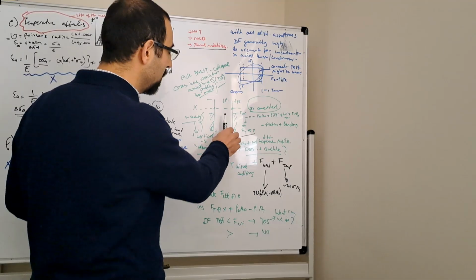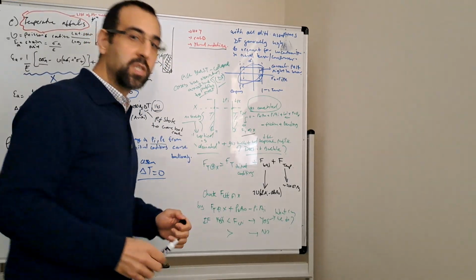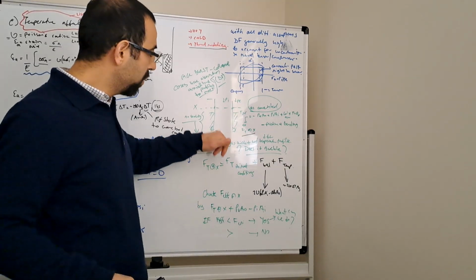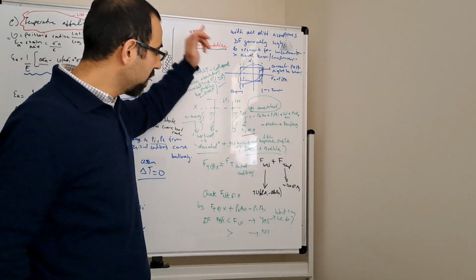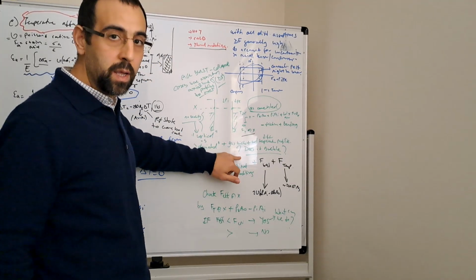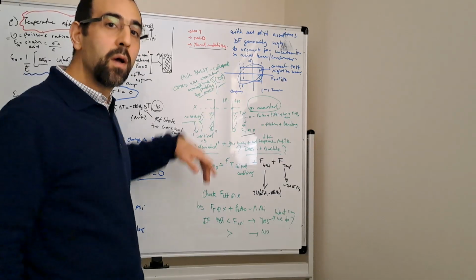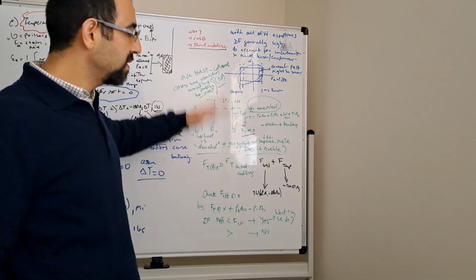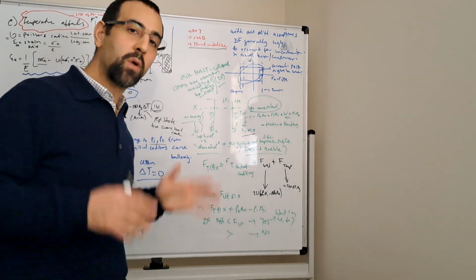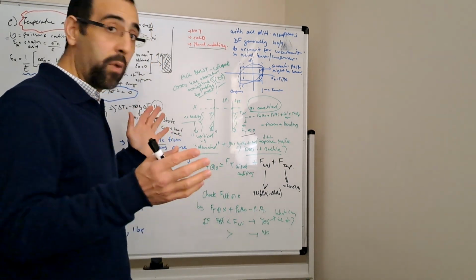Now you have a different internal pressure profile, because of your pressure, wherever you take it from: frac at shoe, full gas to surface, or next hole TD gas to surface. So you basically, taking into account compressibility, come up with an internal pressure profile. Perfect.